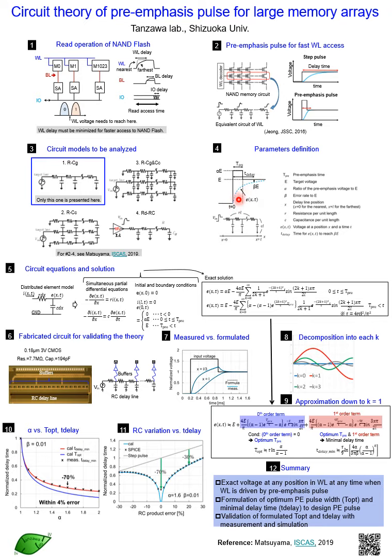Assuming this waveform is from the slowest node of the word line, then you can define the delay time t delay by specifying the parameter beta, which indicates that the slowest node reaches beta E. For example, if you want 1% variation or fluctuations among all the memory cell gates, then you know the t delay as a function of beta.